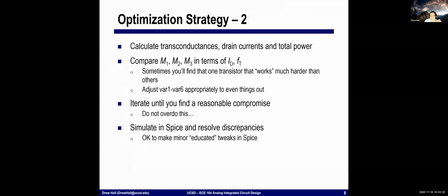All of these things, SPICE will accurately calculate. It won't assume anything. Okay. And so what I want to do is find a good, reasonable starting point for a design, simulate the circuit in SPICE, and then go back and look at discrepancies between the GMs that I calculated and the GMs that SPICE simulates.